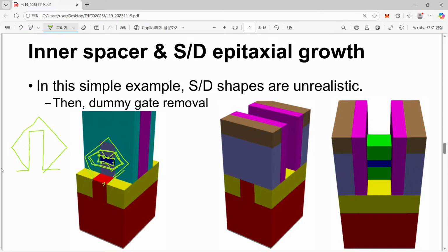However, in the case of our nanosheet MOSFET, it is a combination of fin, and on top of it we also have this nanosheet. And the important point is the shape of this nanosheet. Now we have a certain shape. Oh, sorry. And this one also grows, but this fin is not as tall as the previous fin. This one is really used as a channel material.